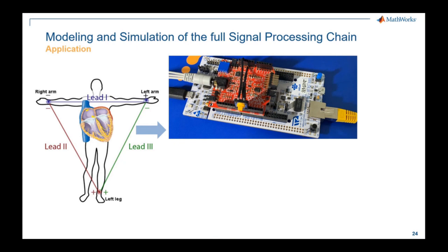So the goal is that once you have created your algorithm, your application, if you are using Mbed drivers in order to communicate with the peripherals that are on the hardware, like an ADC, like an LED, or these kinds of things, then you can retake your algorithm and deploy it onto whatever target that is Mbed enabled. And there will be more than 150 different boards supported with this. And at MathWorks, we have created a package in order to support that. And we are adding more and more boards time after time using this Mbed hardware abstraction layer. That's why I've decided to use this board.